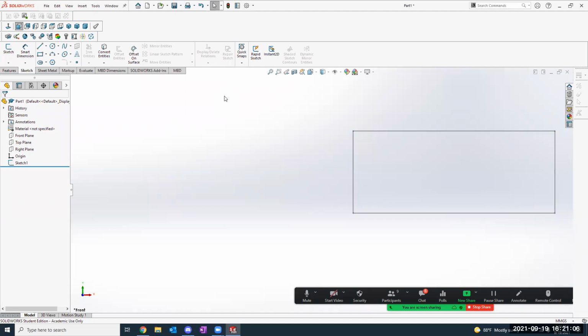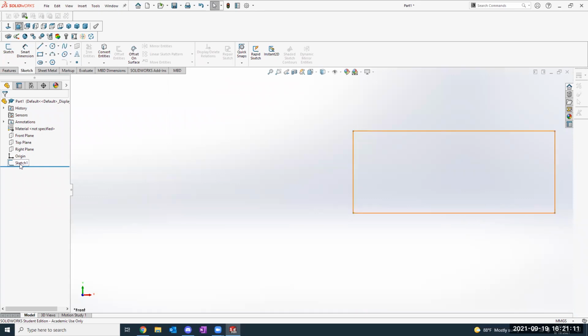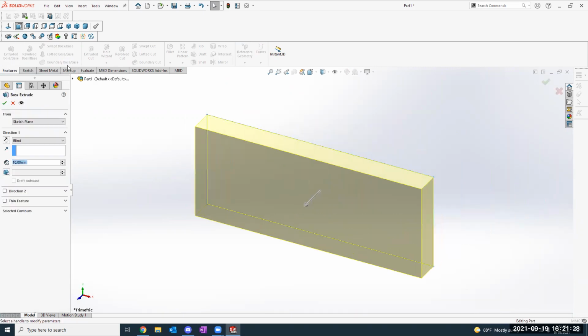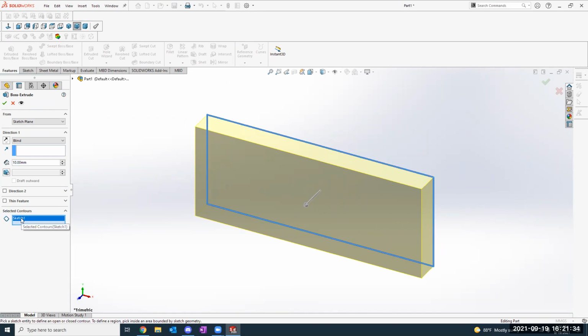All right. So once you're out of this sketch view, you're going to select this Sketch1 if it hasn't already been selected, right? And then you can go to features in the top left, little icon, and then we're going to hit extruded boss/base. So what that's going to do is take your sketch. We've had the sketch selected already, and it's going to extrude it, or pull out that 2D closed profile into a 3D shape. So on the left menu, you see a couple of options.